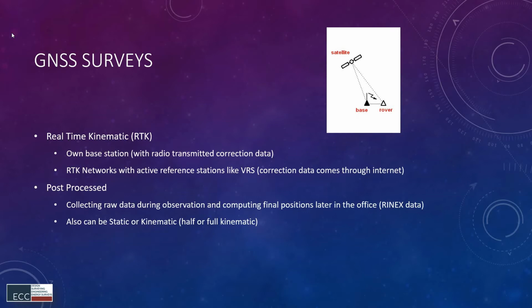We fix its coordinate, and then we just start a new job, and we bring in all the raw data we surveyed. In the second job, we don't have to worry about the RINEX data anymore, because with the RINEX data we fixed our base coordinate. We can export the fixed base coordinate from the first job and bring in just the rover points, or we can bring in everything, select the base point, change the coordinate, and make it a control.